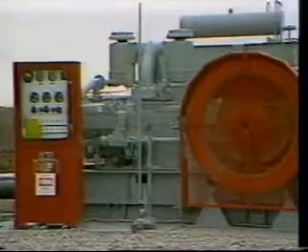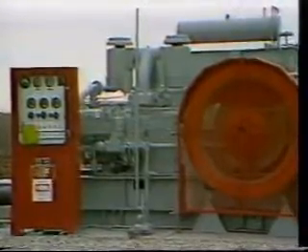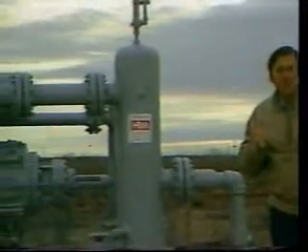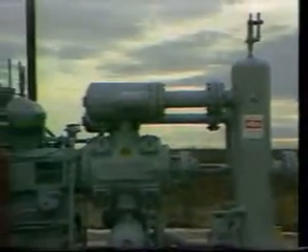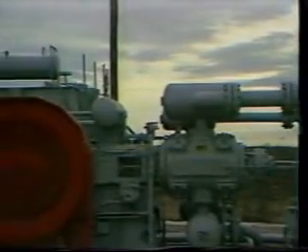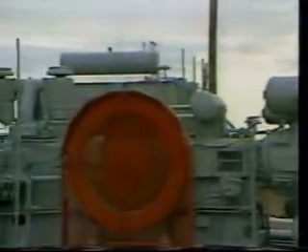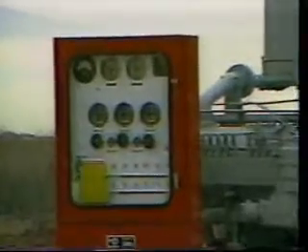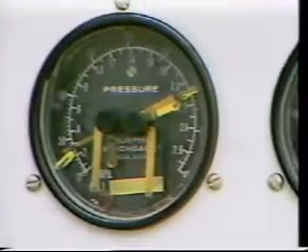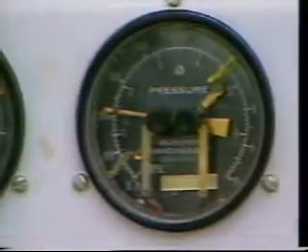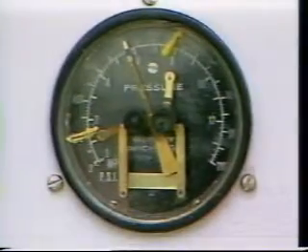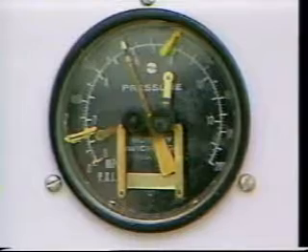After the gas leaves the metering station, it comes through a line to a compressor. Now, a compressor is used to increase the pressure of the gas from a low pressure to some higher pressure. In this case, from 50 pounds to the 800 pounds needed to push the gas into the sales pipeline. This compressor is a 230 horsepower compressor. It has two stages. The first stage takes the gas from 50 pounds up to 200 pounds, and the second stage takes it from 200 pounds up to 800 pounds. The gas then leaves the compressor at 800 pounds pressure and travels to its next stop, which is the drip.